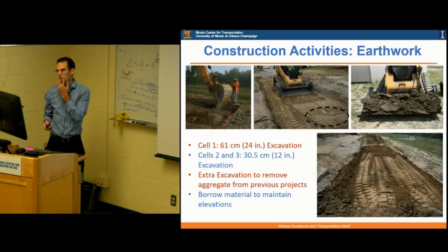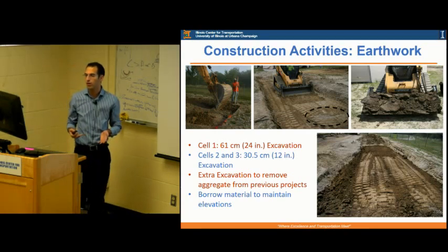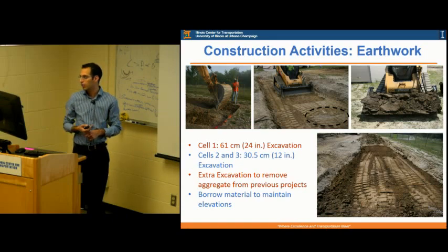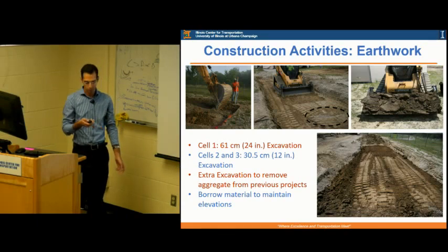So now after we have those applications for the quarry byproducts, we've moved to the construction phase of this project, which took us some time to engineer the subgrade and do all the construction activities. So the basic first step of each construction is doing the earthwork, so the excavations. And in some cases, because this project has been built on an older project, we had some areas where the previous base course material was deeper than our intended excavation depth. So we had to clean those and bring some backfill or borrow material, and then engineer the subgrades or level the subgrade to our elevations.